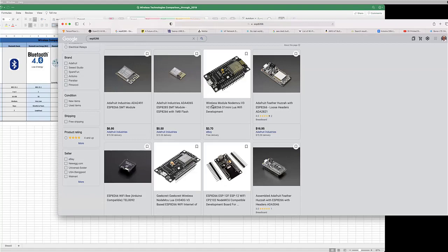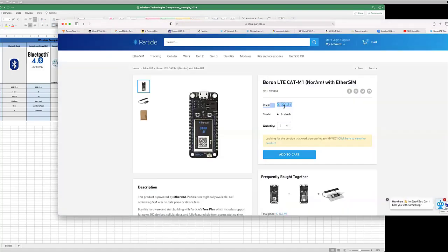If you don't want to use Wi-Fi, you could use a different radio on some of these attached to a microcontroller. So there's a lot of different options out there. You don't have to spend $60 plus a photo eye cost for each sensor. You could do a photo eye plus something else, plus a small microcontroller and a 900 megahertz radio back to a gateway. But that's really on the development side, if you're doing it custom for yourself. There's a lot of consumer grade products that exist already to make this easier.